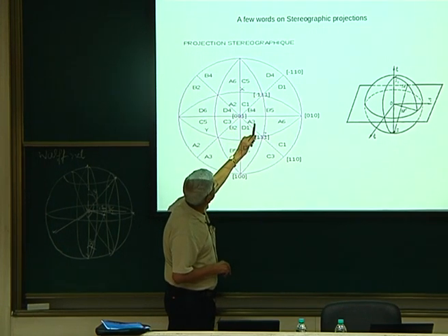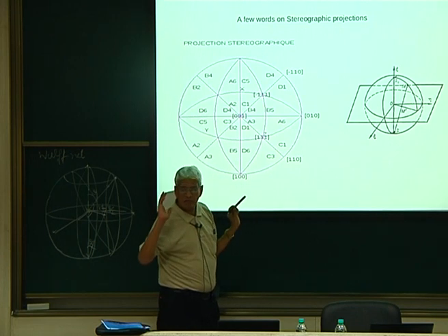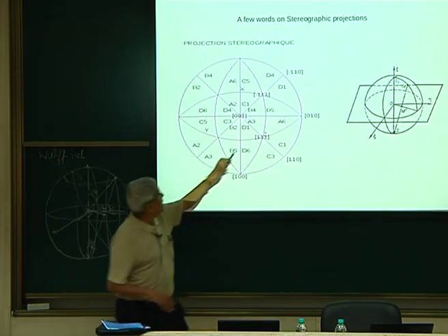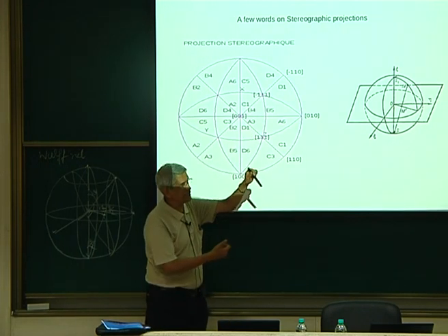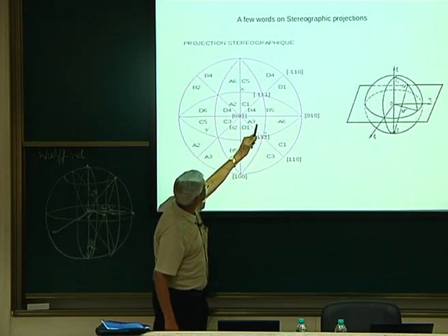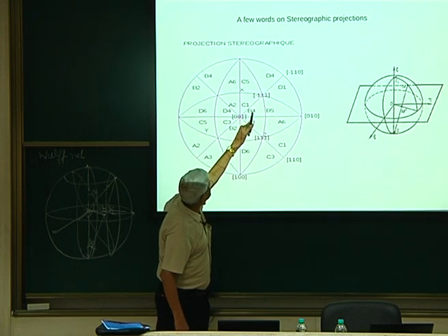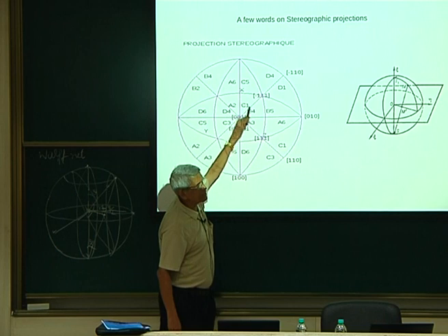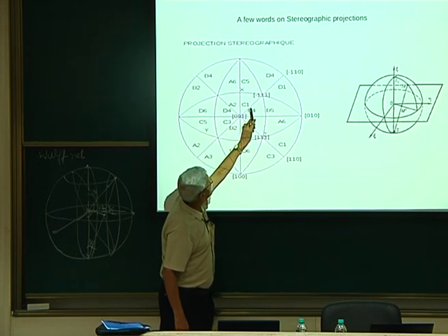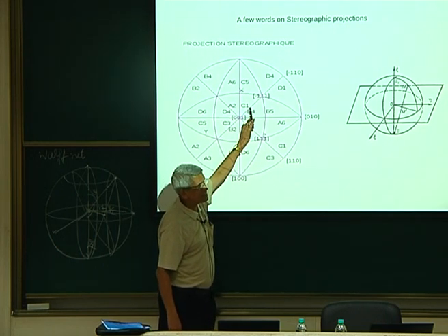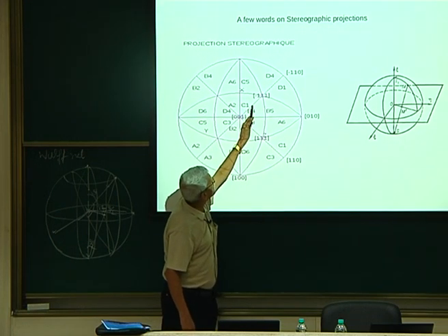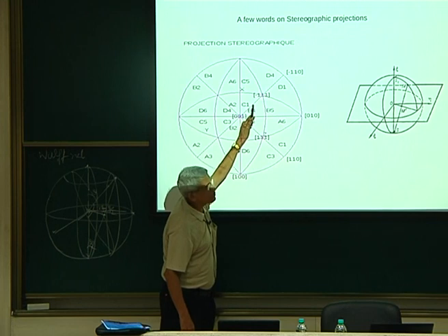Then we know that when we deform that sample, the orientation continuously changes. What is the direction it will be changing? From here, if it tries to change, it will be changed towards the Burgers vector direction. So it will go from here, and when it reaches here in this direction, then two slip systems become active. Then it will start moving here and come to a point 1 1 2.